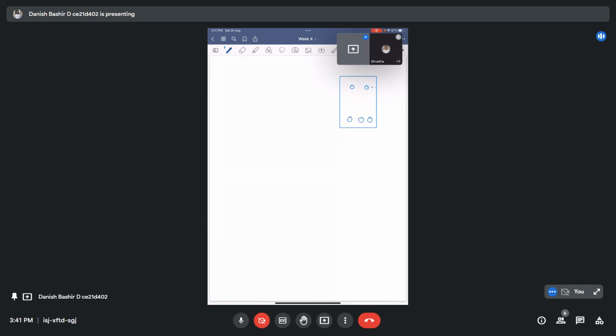We also need this D dash distance. So for the time being, I am assuming these bars, ASC, are 20 mm diameter bars for compression steel. From this I will calculate D dash.